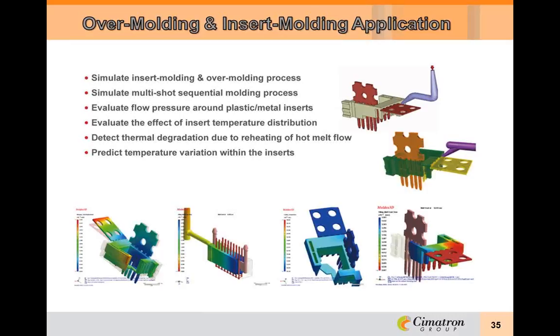eDesign multi-component molding gives you a powerful tool to accurately analyze the interaction of different components and further optimize product design. Users can freely model any kind of metal or plastic inserts and perform comprehensive analysis. With eDesign MCM, you can predict the prolonged cooling time, asymmetric shrinkage, and two-color or overmolding processes, and consider warpage of the different material combinations.